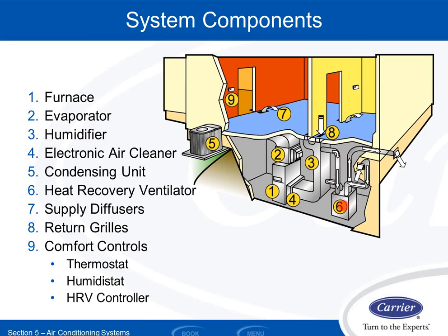So he saves his heating energy, his cooling energy, his humidification or dehumidification energy, and then takes the dirty air molecules and dumps them to the outside, out that path, out the outside wall. Then we take in on the other side of the heat exchanger in the ERV, we suck in fresh air from outside, we run it through that same heat exchanger and pick up all of that cooling and heating energy that we just left there and bring that back into our system. So it is a pretty good energy saving device in terms of bringing more fresh air in without having to pay a bunch of energy to heat it and cool it.